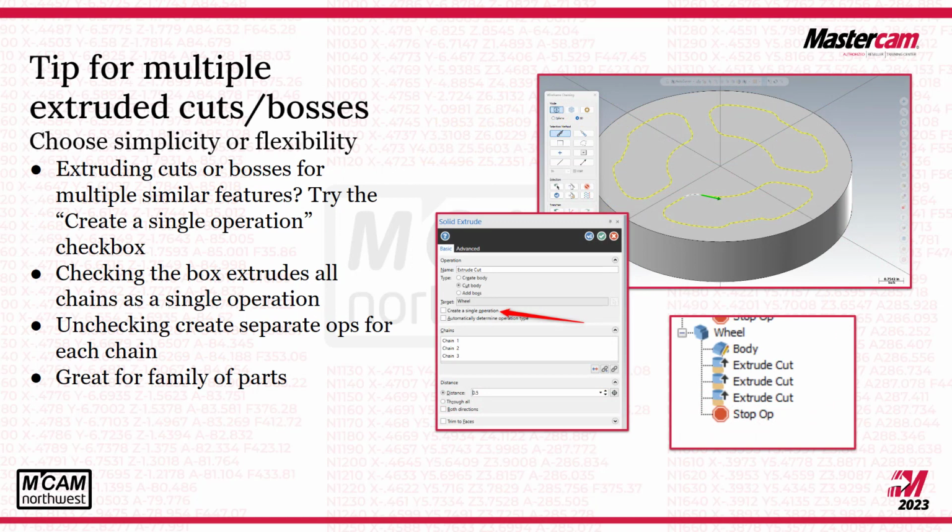extruding multiple cuts or bosses. So let's say you're making a part and you have multiple chains and you're going to make a cut from that, or you're going to make bosses from that, there is a checkbox that is often overlooked inside of the solid extrude tool that will allow us to change the way that this behaves on a base level. Depending on whether this is on or off, we get totally different results.